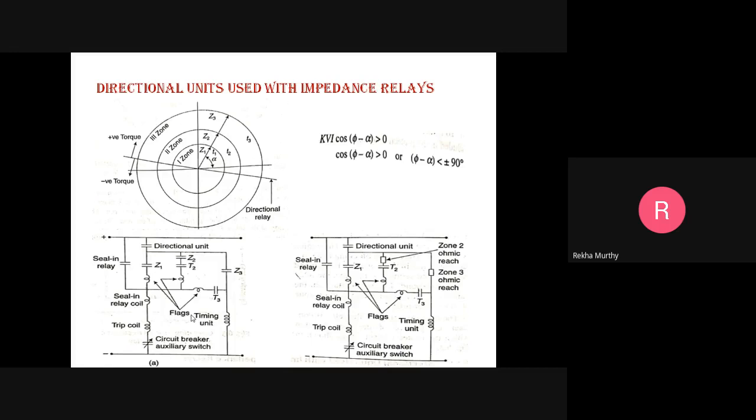A directional relay employs two pairs of contacts. One pair is placed in series with the contacts of the impedance relay and the other pair is connected to energize an auxiliary relay. The contacts of the auxiliary relay, when it is de-energized, short circuit the current coil of the impedance relay. The contacts of this auxiliary relay will be opened whenever a fault occurs in the forward direction. This type of control is very much required to avoid the contact race between the impedance relay and a directional relay in interconnected or double circuit lines.